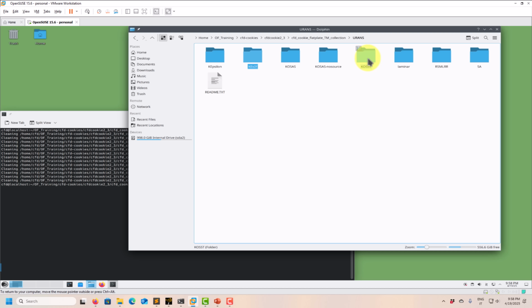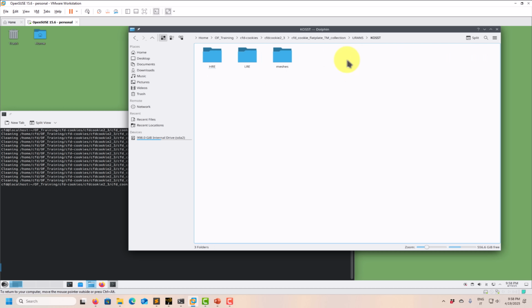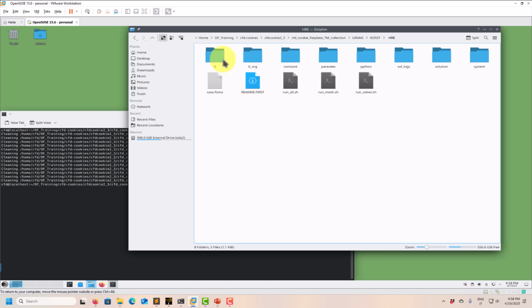So remember that the SAS is based on this, and then you have those extra source terms, and then you will add those extra behaviors and coefficients and so on. So let me go here, and K omega SST, we know that we have it in two flavors, high Re, low Re. Also remember K omega SST, you have the wall distance and so on, so we have covered that, but just to remind you. But the K zeta is exactly the same as what we have done in the steady case, okay? When it comes to boundary conditions, remember then you need to adjust your system directory for the numerics.